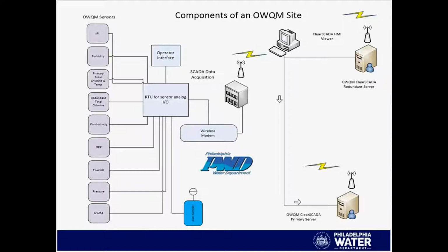But above the RTU, I have what we call an operator interface. And for the instrument guys out there, I can't tell you how valuable having an interface on site is. Essentially, that's taking the computer from the remote location or from my office and putting it on site. So it allows my technicians and engineers to see the data as it's being transmitted, so they know that the value going into that RTU is the value that is being transmitted, and it's a very helpful feature.